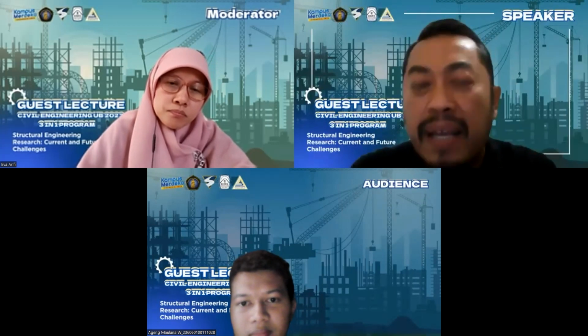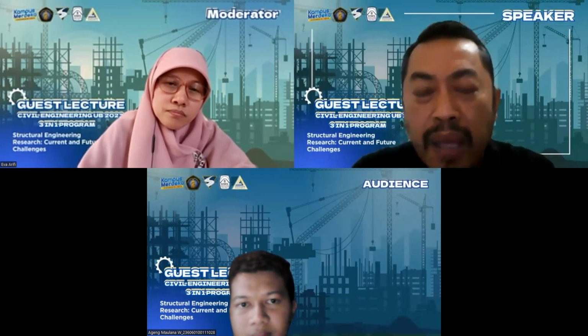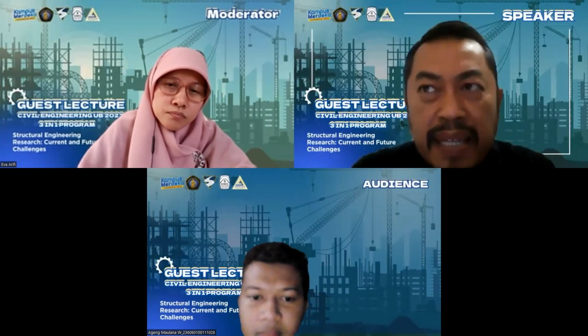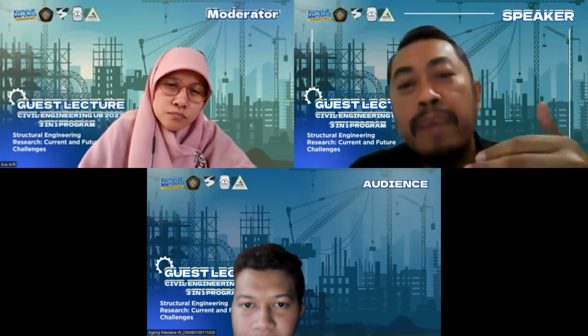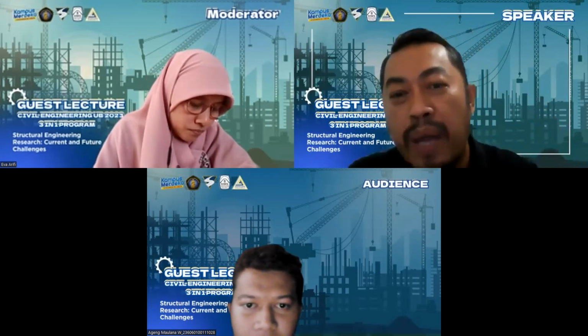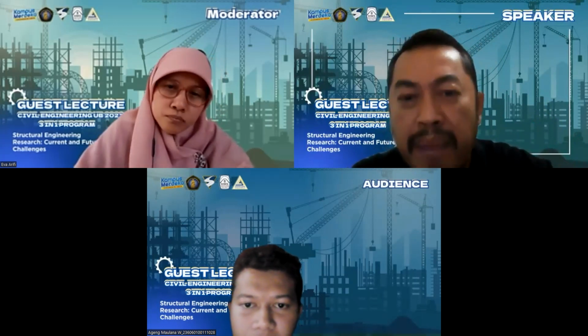You can search my paper on, I think, Buildings for punching shear. We put 0.85 if you have a percentage of RCA less than 90%. I'm not sure, I think less than 85%. But if you have more than 85%, then you have to multiply by probably 0.85. Yes. But if you have less than 75%, you multiply by 0.9.